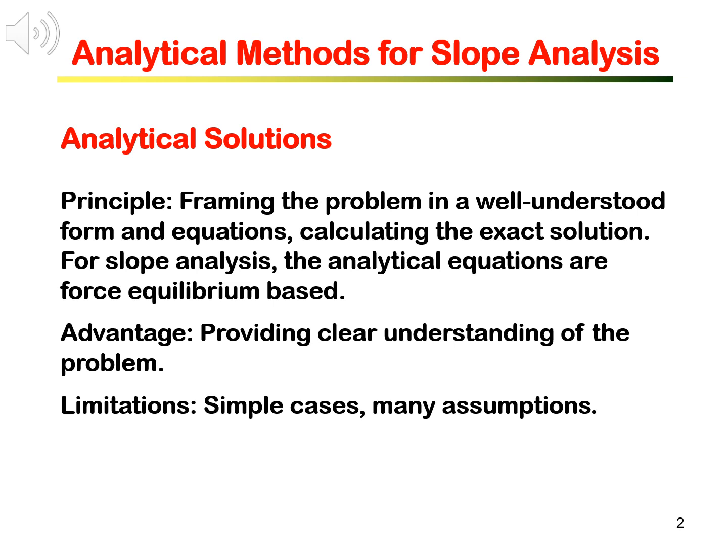Then, a set of logical steps can be followed to calculate the exact outcome. For slope analysis, the analytical equations are force equilibrium based, calculating the forces pushing the slope down and the forces resisting the slope sliding.